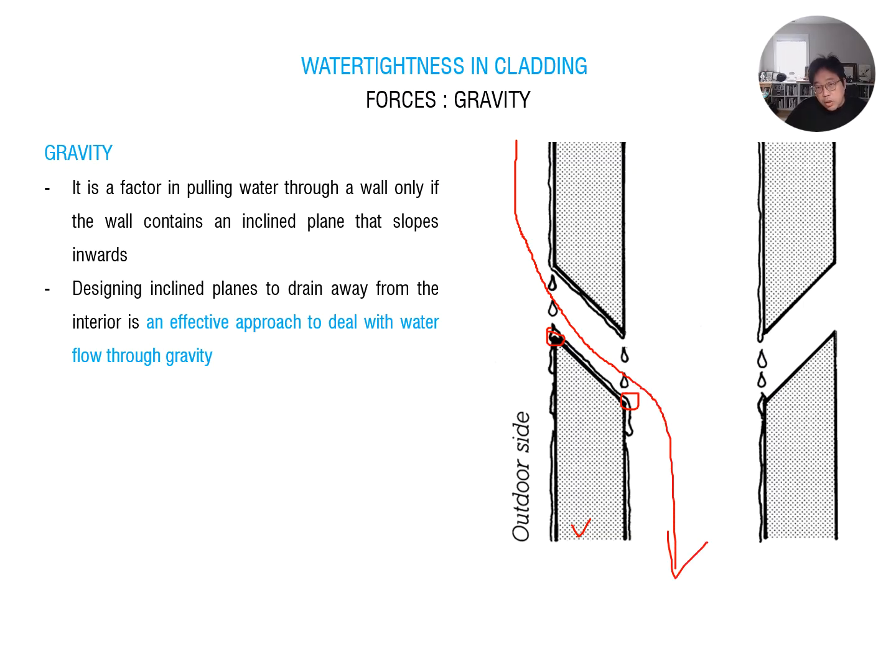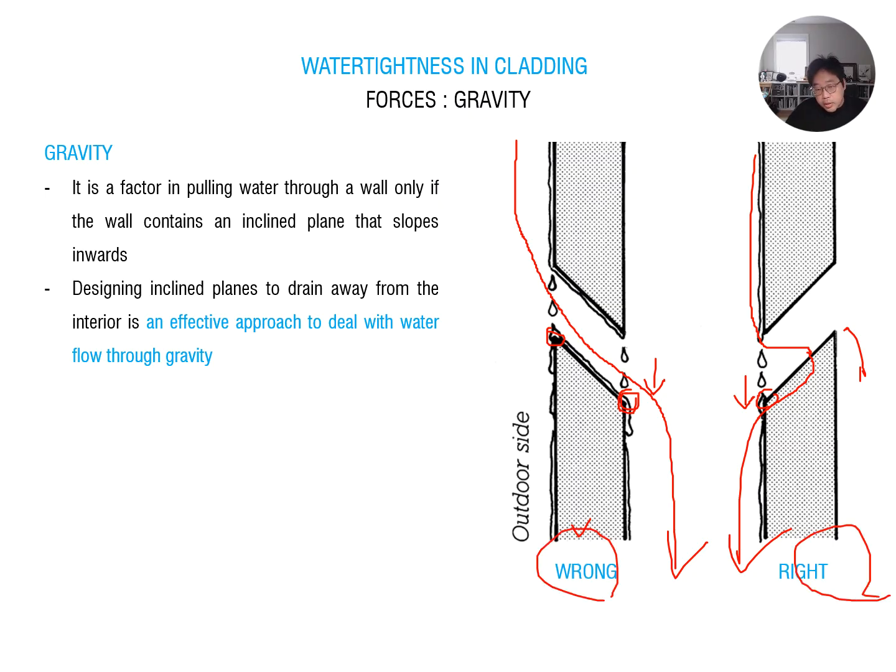As we learned, water has to get out of our assemblage as much as possible. That's why, rather than placing this much lower, you can consider making the outside lower. So when water comes in, gravity does not carry it into this assemblage, and the water comes out again from the assemblage. Therefore the panel plane constraint is to incline the slope inward when you have a joint panel. So that is more to consider about your panel design rather than these conditions.